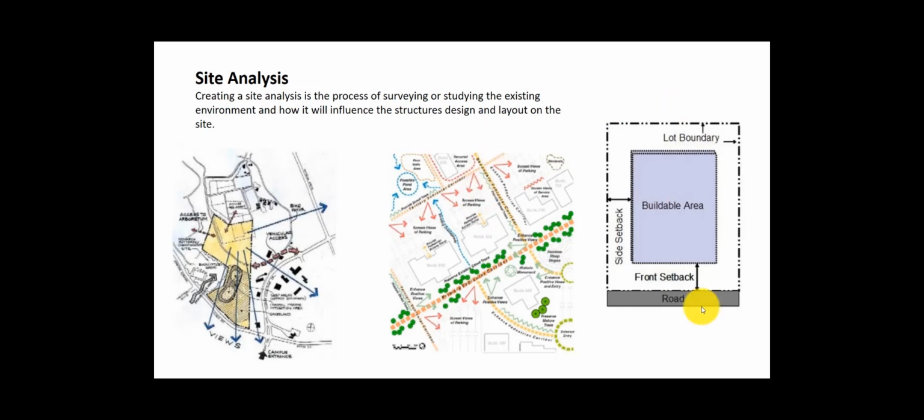Every site has site setbacks from the property line. So this phantom line, the line with the two dashes there, becomes the property line, and there's a front setback, two side setbacks, and a rear setback. And that will give you kind of that buildable area. There's also a percentage of area within that buildable area so that someone can't build right out to the setbacks.